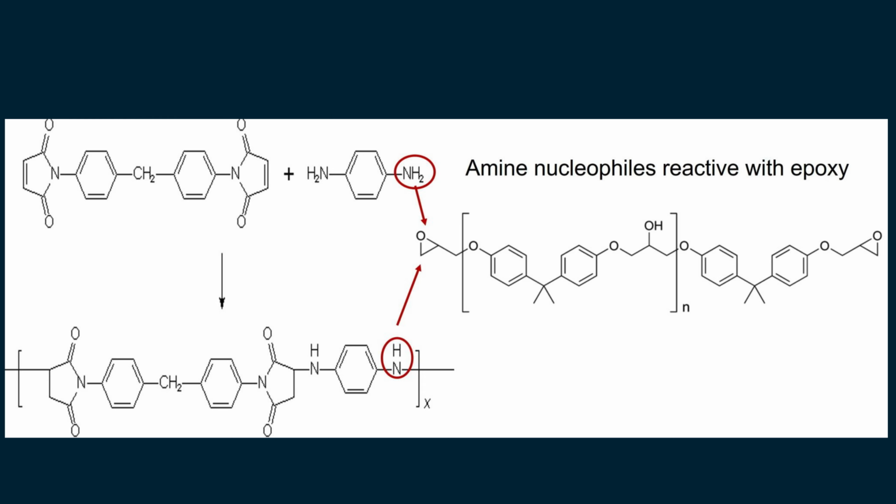After blending with the resin, the mixture has a pot life of about 6 hours at 25 degrees Celsius. If the mixture remains unused beyond the pot life, it gradually undergoes B-staging at room temperature. B-staged MPDA epoxy materials are useful for manufacturing prepregs, filament winding resins, and solid adhesive forms such as films or powders. Full curing typically occurs at 150 to 175 degrees Celsius, after which a post-cure at approximately 175 degrees Celsius is performed to achieve optimal properties.